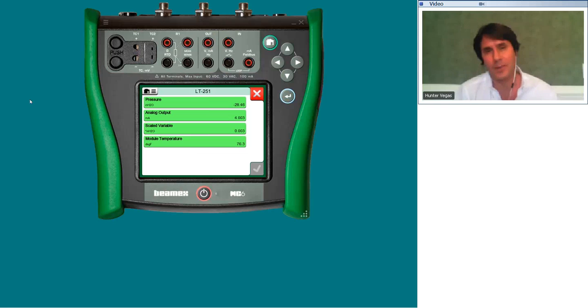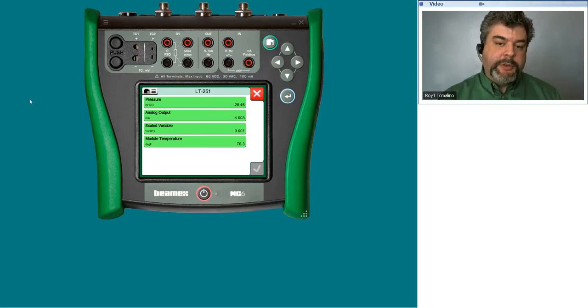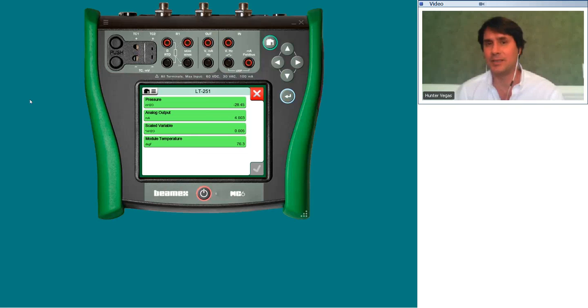And I'm showing right now, can you see the MC6 on the screen? Yes, sir. So I'm looking at the measurable variables on this transmitter, and right now, vented, the process variable is actually showing minus 28.46, so that's literally how we get that number easily. Yeah, and if Roy moves that seal around even a little bit, you'll see that reading change. While it's possible to do a bench calibration of a seal installation, where you can see it moving, it doesn't take much. It's way easier to do it installed in place in the field, and that's why the flush rings are so useful, because you can just block the seal, usually with an isolation valve. You open up the flush rings and vent them, and now you've got a place to easily apply pressure, but you don't have to physically move the seal, because, like I say, their elevation sets this number. Thank you, Roy.